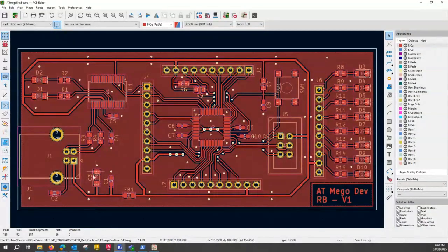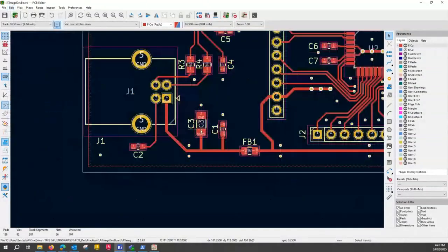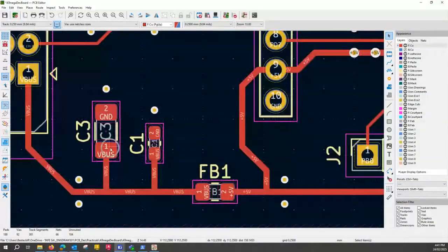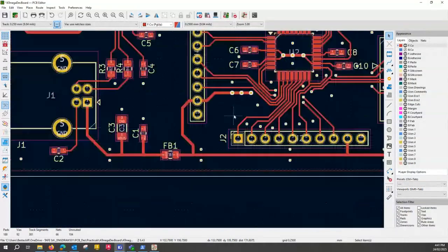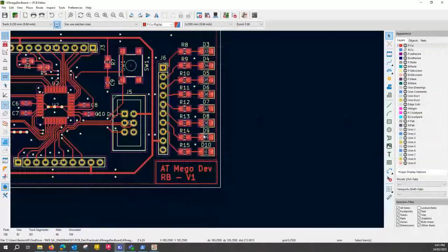There's one more thing to do, and this is the capacitor. Usually whenever I'm working on a board, I remove my fill. So unfill, zoom in. Because this is a polarized capacitor, we need to indicate which side is plus. You can do it the same way I'll show you. The diodes are done, because diodes are polarized. You can see that yellow line coming from the back, but not from the front, and that gives this sort of indication of polarity, that this goes to the ground. We could do the same here.